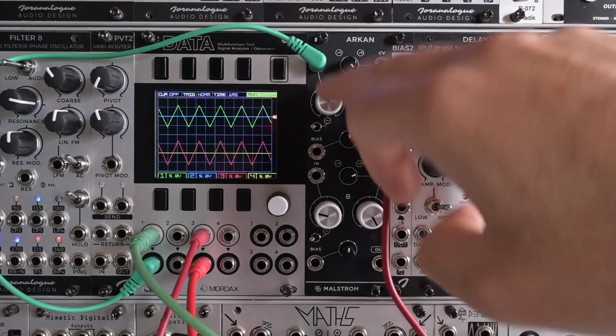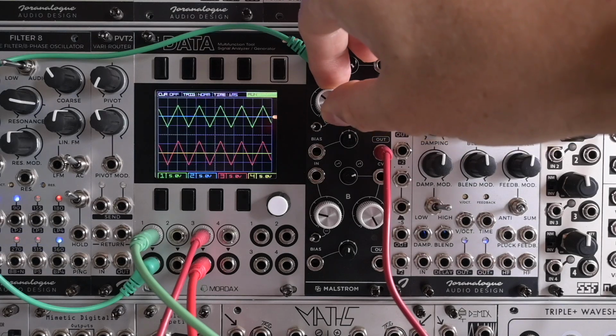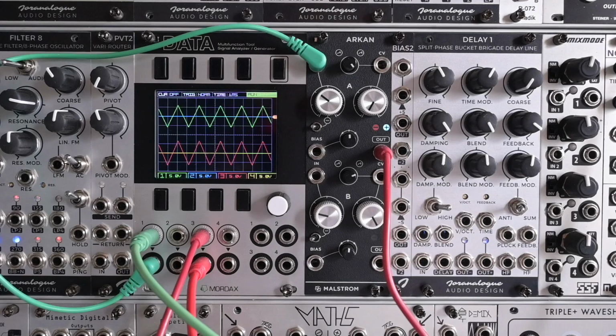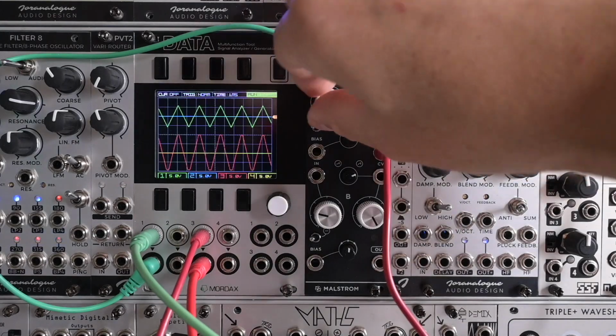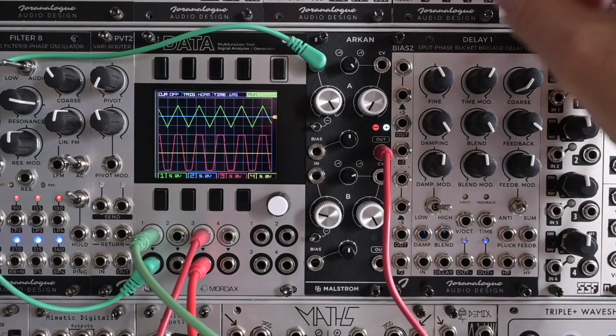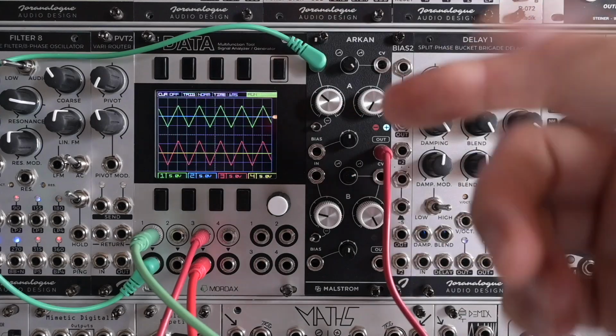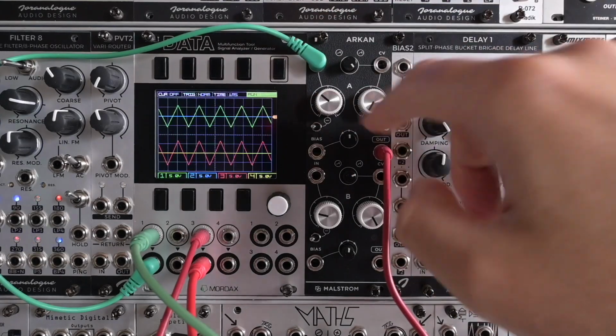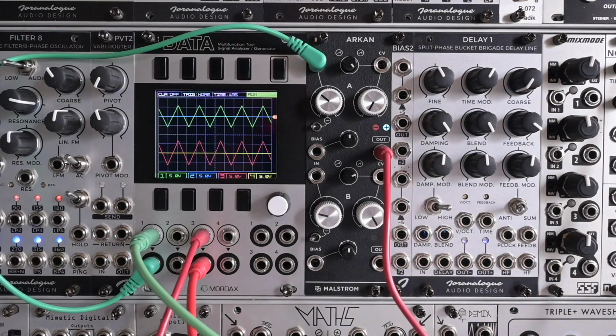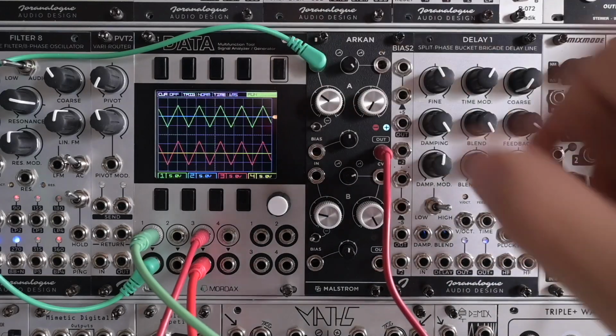And then when you turn this completely to the right, we're actually having a 4 times amplification, which is plus 12 dB. And I quite like it this way. But if you really need this knob just to attenuate, then you can make it happen.